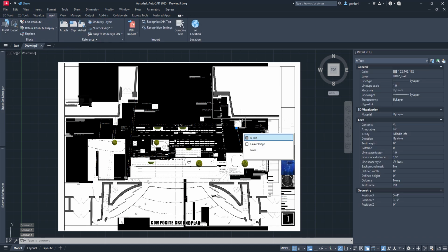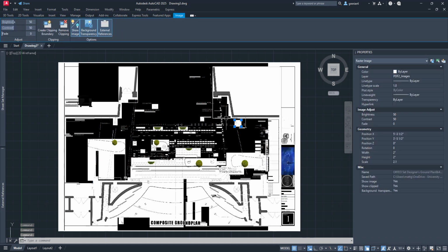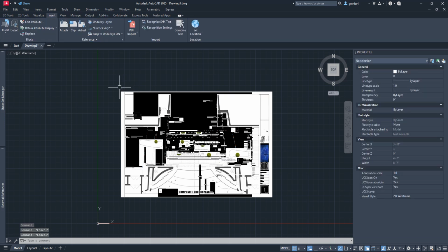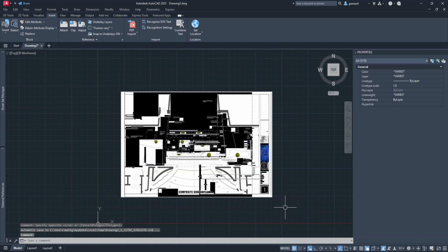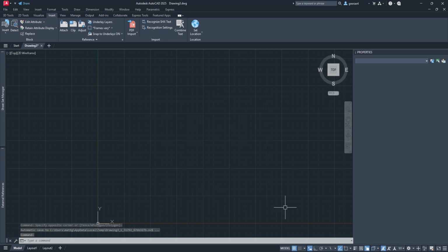There are some polylines. There is some geometry in this file that is vector based, but there's a lot of raster images. So again, this is really not constructive for us. I just wanted to show you what would happen if you tried to import a PDF this way. We're going to use a different method to do this a little bit more effectively. We're going to attach the PDF as an externally referenced file. So what I'm going to do is type